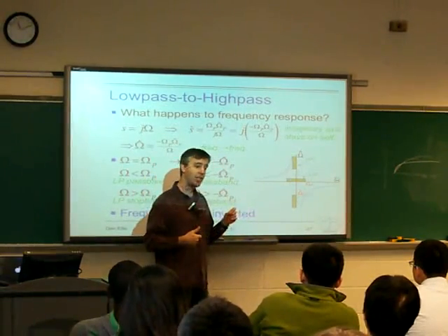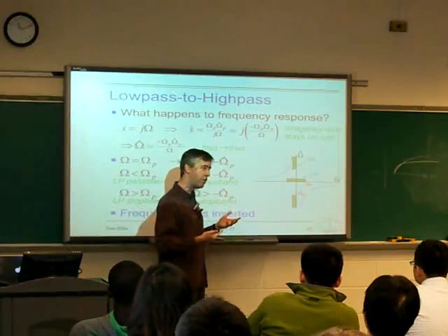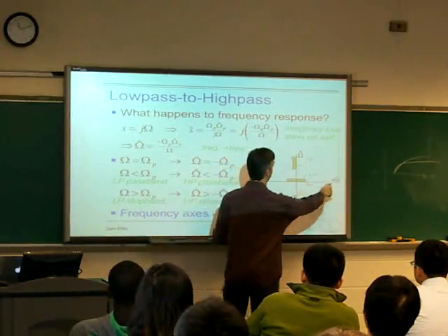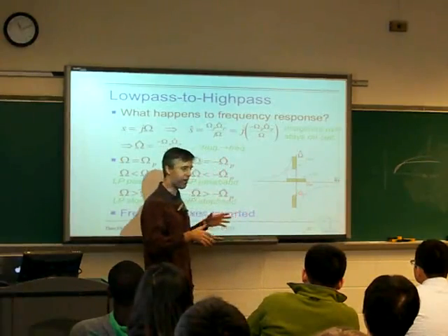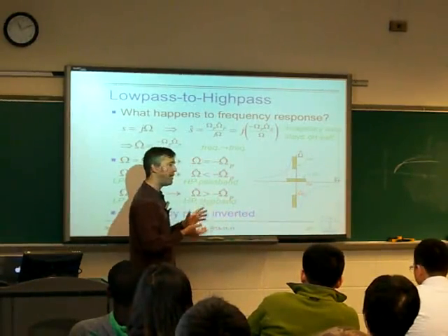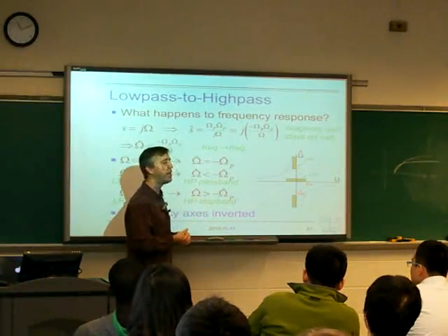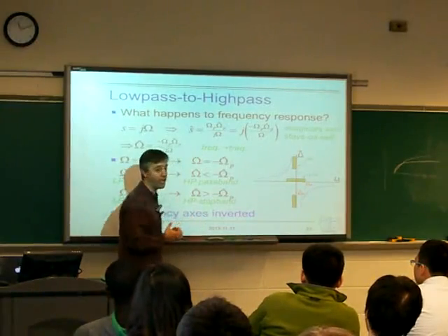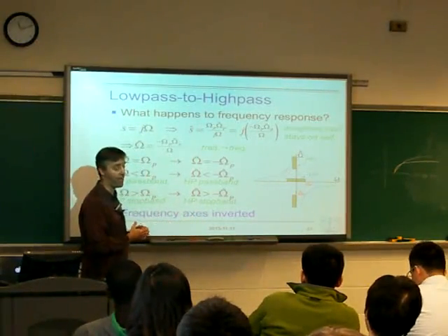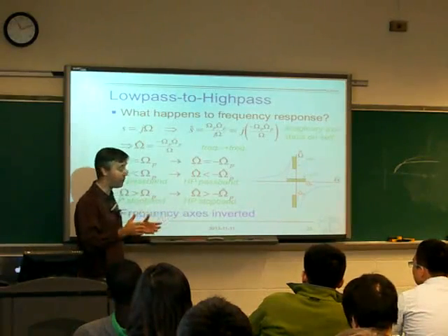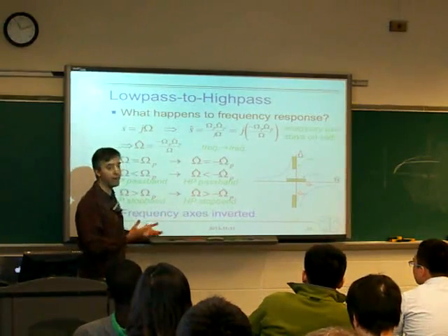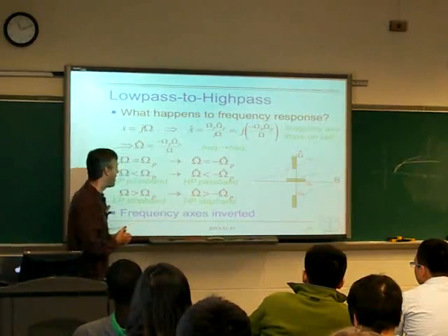The way that happens is that you end up doubling the order, because now you can't use a simple reciprocal. You have to have some kind of quadratic thing. And so you end up with a bandpass filter that has twice the poles and twice the zeros of the low-pass prototype. But apart from that complication, it's basically the same kind of technique. And you could imagine doing it for more than one pass band, but that's a more exotic thing.